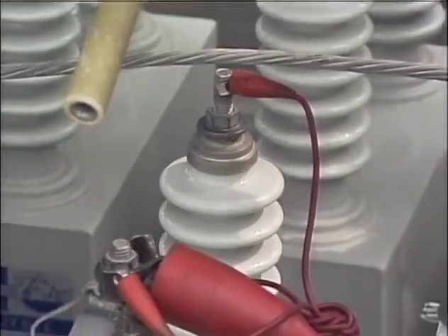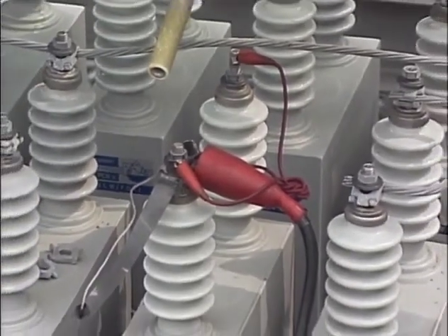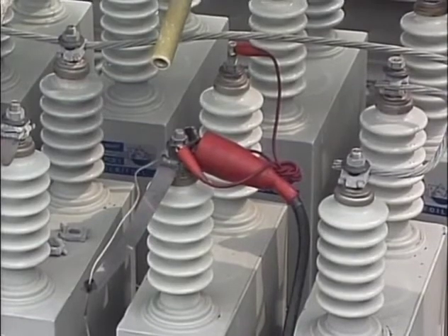The purpose of testing the capacitance of a capacitor is to determine if the unit's capacitive elements are partially failed, short-circuited, or open-circuited. We're going to look at three common methods of capacitance testing. Typically, capacitance is checked by applying voltage to and testing one capacitor at a time. For this check, the unit is disconnected from the bank.